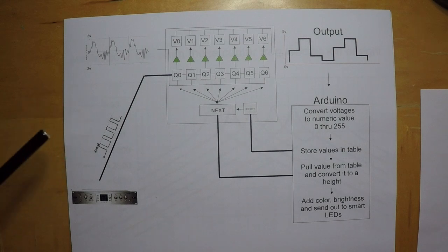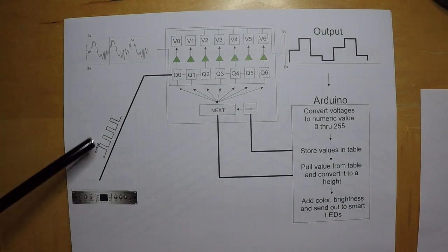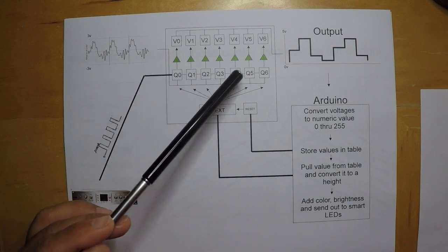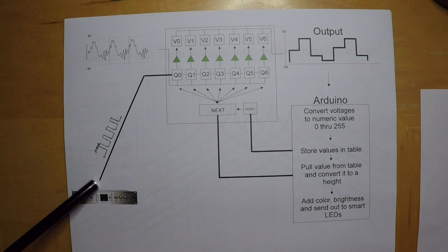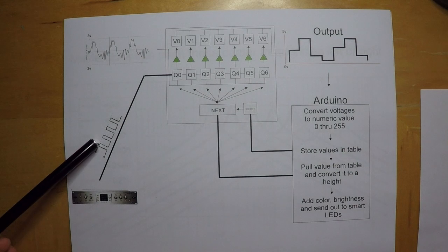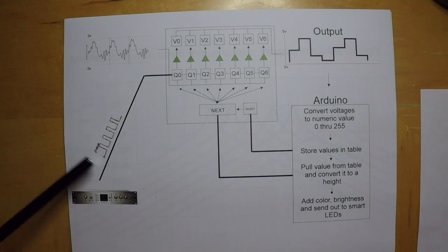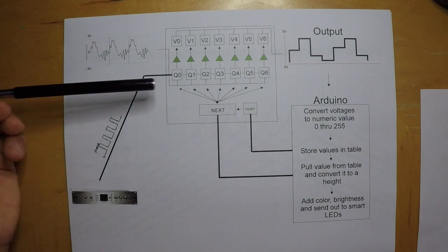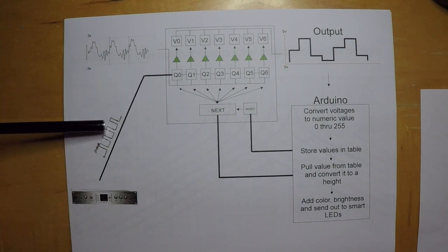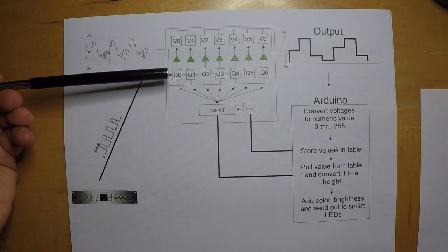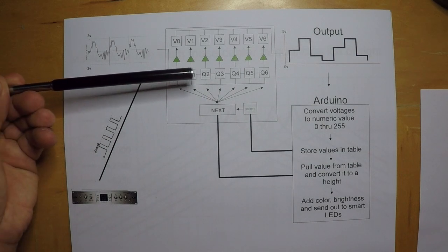Another thing to keep in mind is that these filters are all being driven by a master clock. This is not audio. This is a very steady pulse train, and these filters are using that as a reference signal. I just want you to imagine that if I were to take this pulse train, let's say this was pulsing 1 time a second, and I made that pulse train go 2 times a second, all these filters would shift in frequency this way.